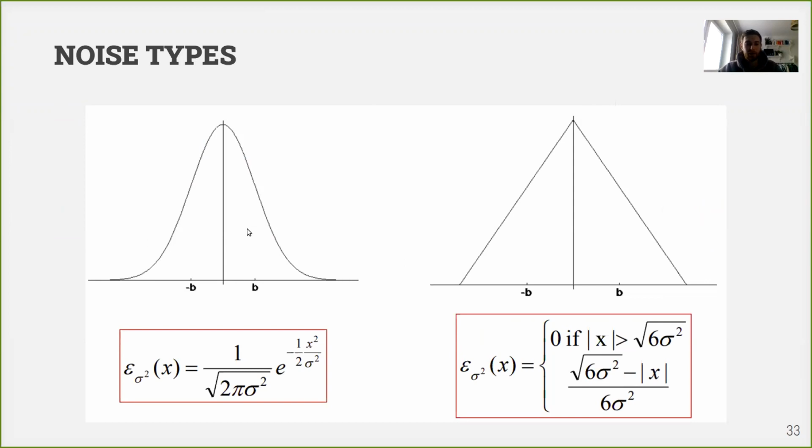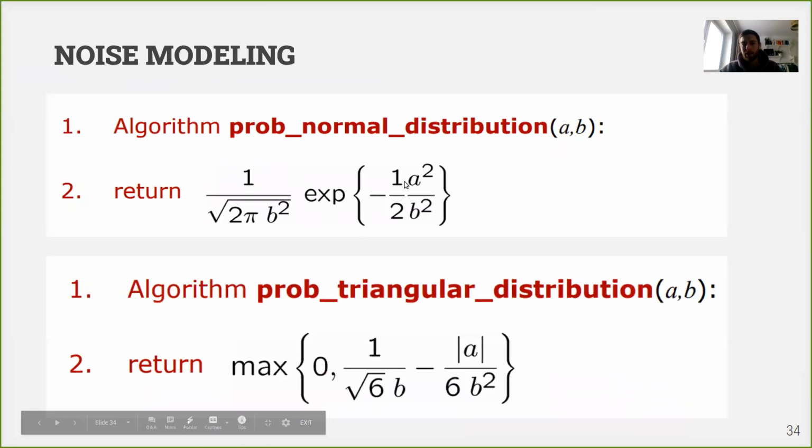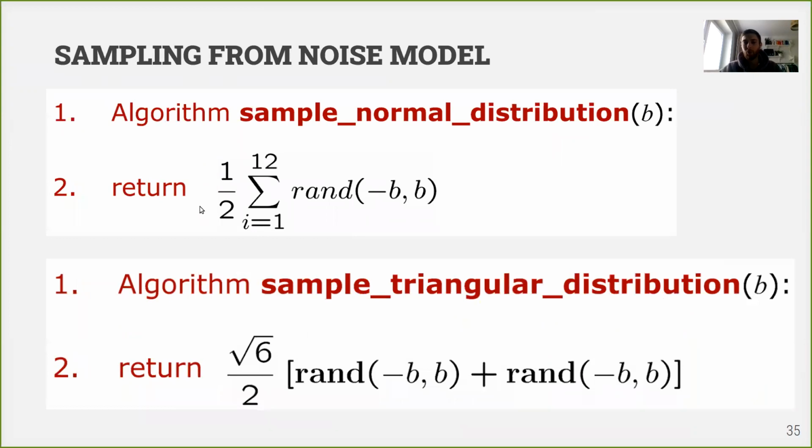If you know, for example, that the error model of your motion is multimodal, and there is not a single Gaussian distribution but a mixture of Gaussians, you can still represent it. But this equation will become more complex, and then probability estimation and sampling will become more complex. You will have to program it somehow.